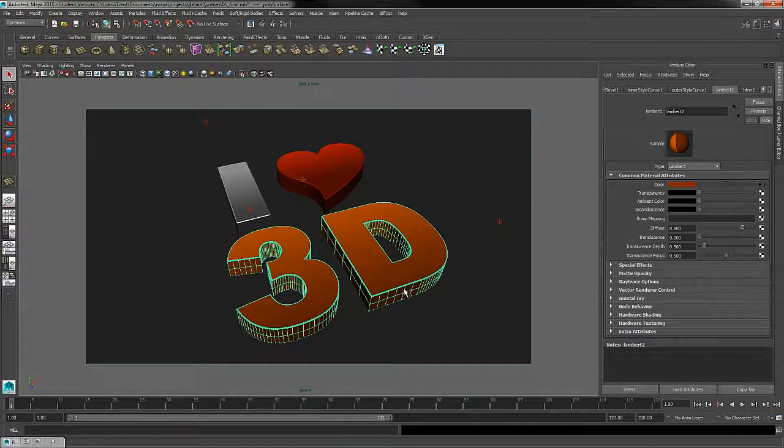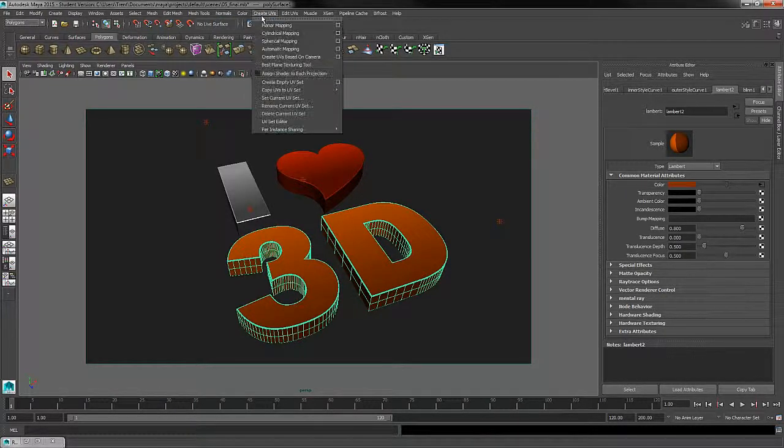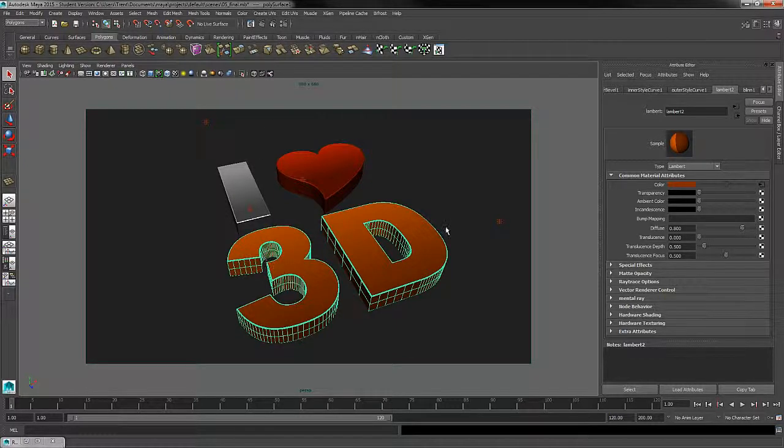So we got into how we can work with normals. So as far as menu tools, we learned how we can use our polygons menu set, how we can adjust and modify normals, how we can work with our UVs to project planar UVs onto our geometry. And by the end of stage 2, we had some nice dynamic material textures applied to our 3D objects.